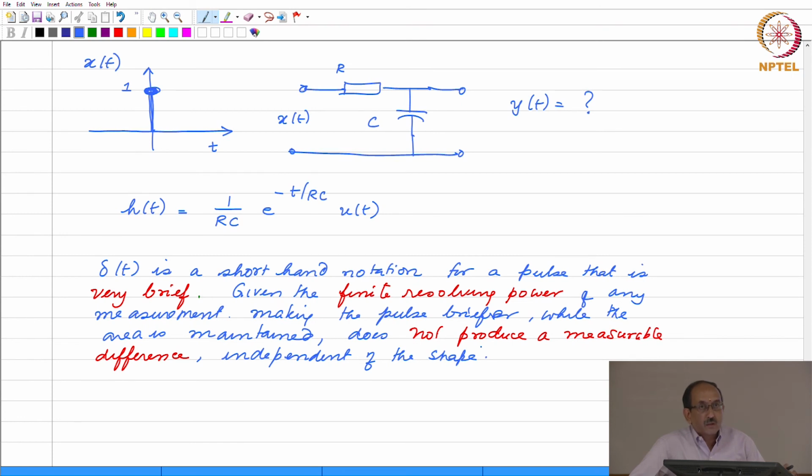So, just to put this in context, Professor Sarathi has this high voltage lab, which is in the same corridor as ESB 127, and it is a huge, very high ceiling lab where we get transformers from all over the country, and there he does testing, and one of the things that he does is impulse response. So, an extremely high voltage discharge that is really brief is applied to the system, and then measurements are taken, and that extremely brief high voltage discharge is the equivalent of an impulse in practice. So, this is really used in practice for measurements such as the one that I just mentioned, and theoretically what you do is analyze such signals as impulses. So, that is where the use is.